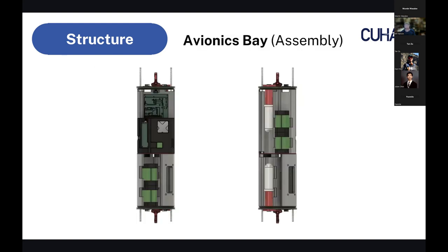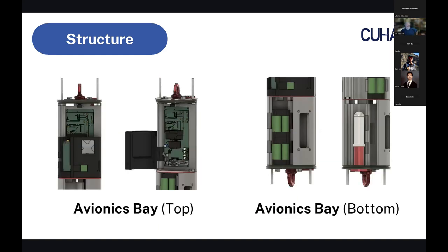The avionics bay sled is constructed from 3D printed ABS plastic because of its temperature resistance and radio transparent property. The avionics bay is divided into two sections, the top and the bottom, separated by a bulkhead, which are joined together by M8 steel studs. The top section is mainly made to protect flight operating components, and is divided into the fixed part, used to attach the PCB and the battery holder, and the hinge part, used to attach the telemetry board and GPS module. The bottom section is made to attach the camera controller section and battery holder.